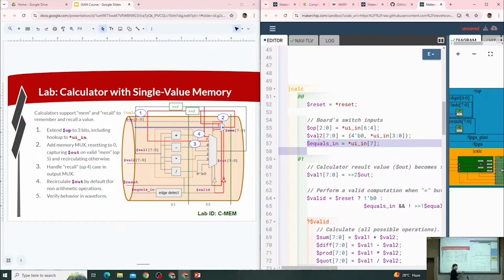And then that marches through and can be inconsistent. If you take that approach, then you retime the expressions that involve reset, and now you're applying the reset differently. But if you're applying a dollar reset pipe signal, and you move the expressions around, the behavior is still consistent, it's still the same.